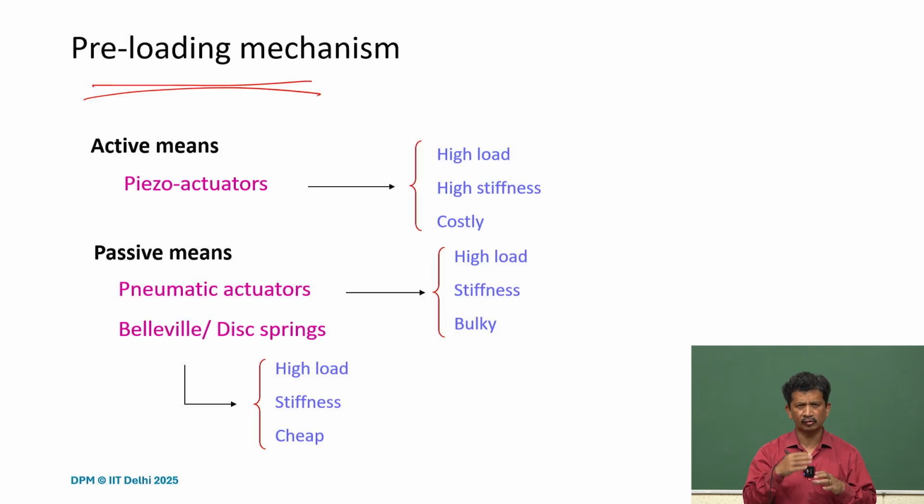So it's by the geometry. Here the principle is different: at the other end we develop a preload mechanism that is constant, so that it always applies the same preload to the air bearings, closes the gap, and maintains the same air gap. So, form versus force closure.